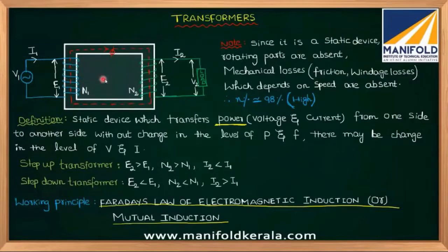Let me ask one more question. If they are not electrically connected, then in the primary winding, EMF is induced, and it's common sense that it is connected to a voltage source. That's why it will take some current, so flux will come, so EMF will be in the primary winding. Because of the source, it's happening. Now tell me, in the secondary winding, how is EMF induced? Do you have any source on the secondary side? No. Very good. Then how is E2 induced? E2 is also because of this flux, the core flux only. But this flux is due to current flowing in the primary winding.